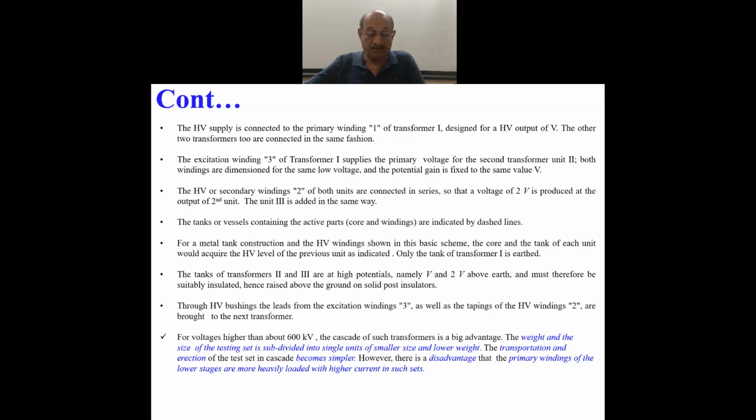The transportation and erection of the test set in cascade becomes simpler. However, there is a disadvantage that the primary windings of the lower stages are more heavily loaded with higher current in such a set.